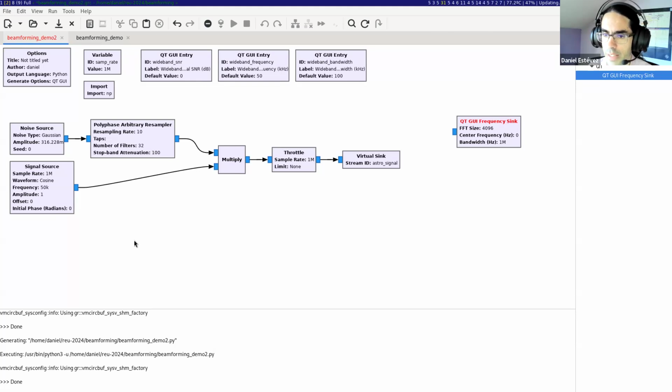Even without any antenna plugged, we received some noise, and the reason is because of the electronics of the receiver. So let's think I have two antennas or a radio telescope composed of two receivers. Then each of those receivers is going to have its own noise because it's generated by its own electronics.